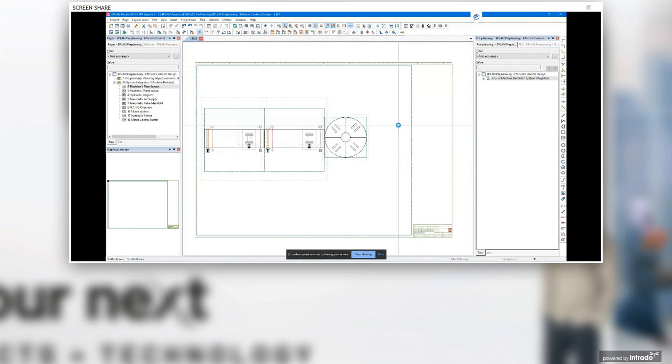Then along this conveyor system, I'm going to place a couple of robots. So I'm going to select this robot using my tab key, which is typical EPLAN functionality. I can rotate my symbols. I'm going to drop one robot here. I'm going to drop another robot here. I'm just going to put one more robot here in this corner. And I'm just going to drop one more down here. So you can have different variations. So up to 26 different variants are available per macro.